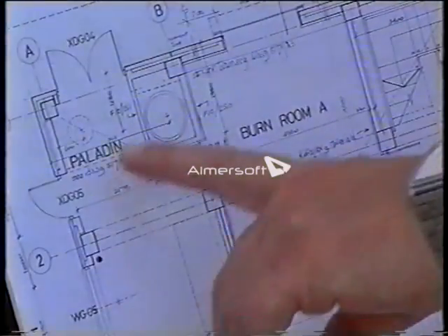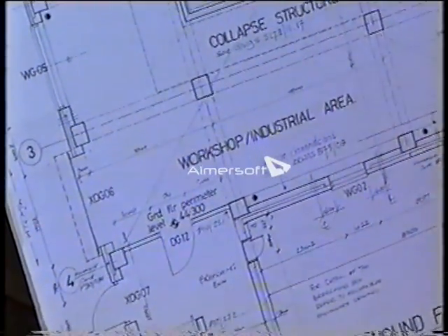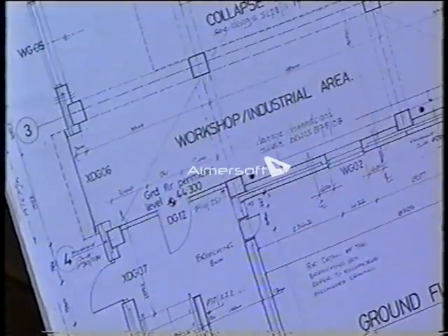The internal design or layout of a building can significantly affect fire growth and smoke logging. This may mean that the passage of smoke and gases is unpredictable. Before the fire floor is ventilated, it is essential to ensure that the resulting air movements will be appropriate for effective, safe ventilation.